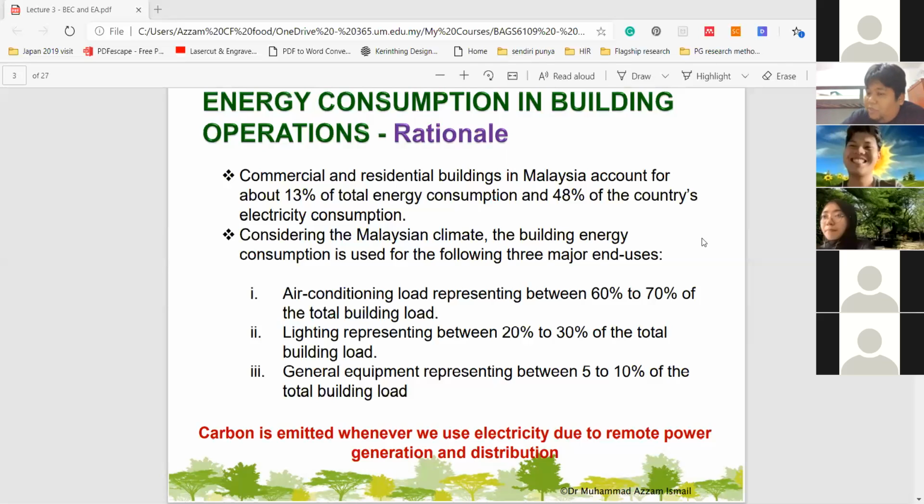Perhaps you can set the temperature inside the refrigerator a bit higher, rather than putting it at 16 degrees, perhaps you increase it to about 18 or 20 degrees. The food will not deteriorate so much even at 20 degrees. If you put it at 16 degrees, after a little while your fruits and whatnot will definitely freeze up. And for your freezer, you don't have to set it at -5. You can set it at -3 or even 0 degrees. If you can do that, it'll be great.